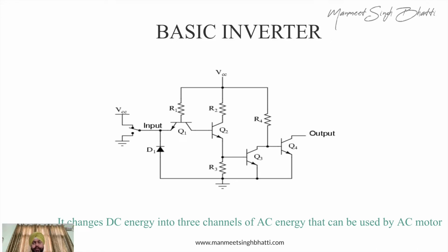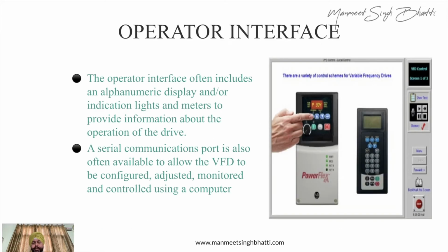It is always an on-off kind of switching, where you get a complete waveform in a similar fashion, so you are getting the AC waveform. So in the beginning we converted the AC to DC, we smoothened the curve, and then again we converted to AC. Here we have control of the switching, so here we also control the frequency. Based on that frequency, you are able to control the power.